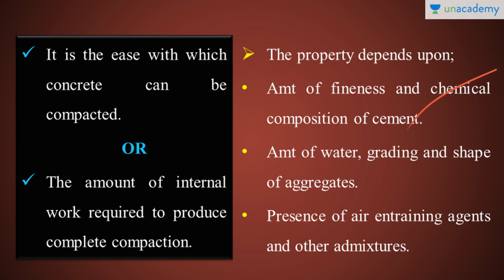Fineness of the cement plays a vital role in the workability of the concrete. The amount of fineness is directly proportional to the workability actually. More cement content requires more water, and it also helps in the formation of more cement paste. This excess paste in the concrete matrix helps the internal particles like fine aggregates and coarse aggregates move easily. So this increases the workability of the concrete without getting into a state of segregation.